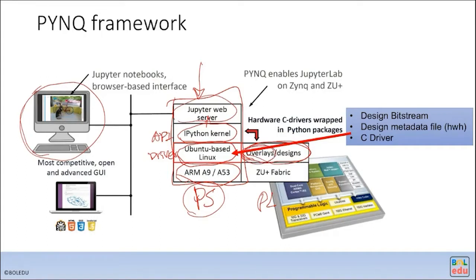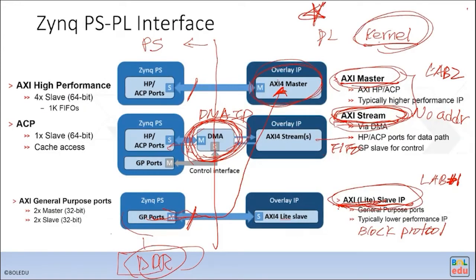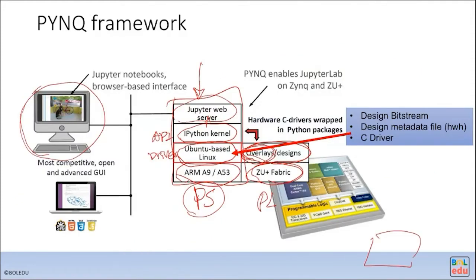In order to communicate with the host, the PYNQ framework provides a set of IPs. For all the kernels, in order to hook onto the AXI interface, which is the boundary between PS and PL, you need some kind of adapter circuit, an adapter IP.